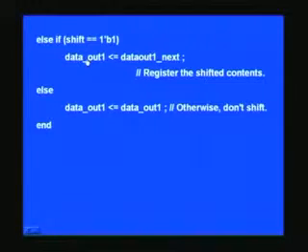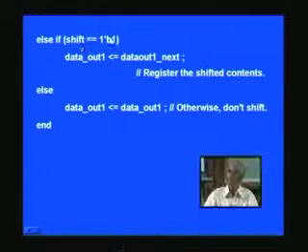This will speed up frequency of operation. That's why all time-consuming computation are always done outside using assign statements, and we just transfer the contents when the clock strikes. And the comment is clear from this. And if shift is not to be done, for example, if shift is 0, this block will not be processed.